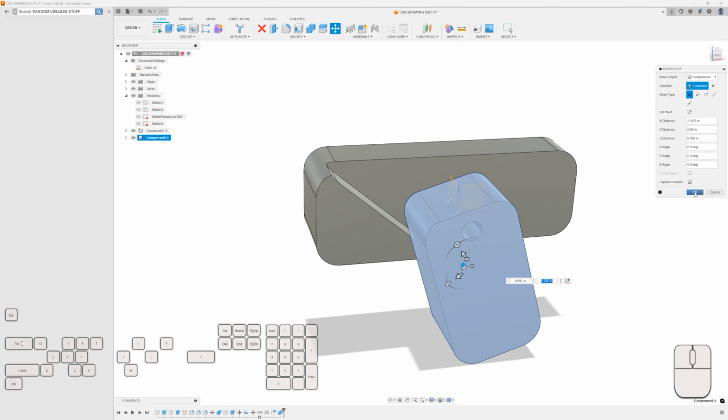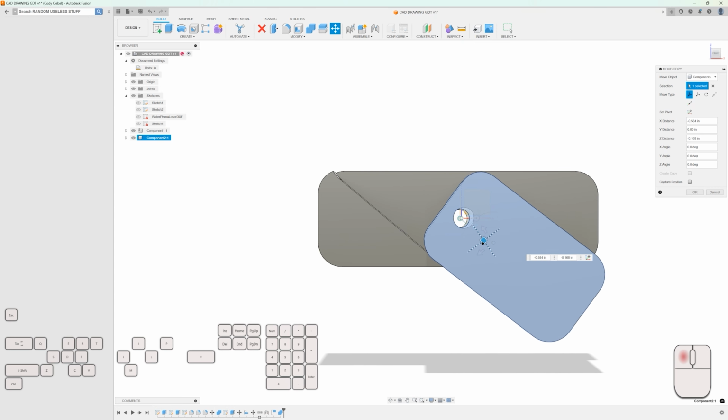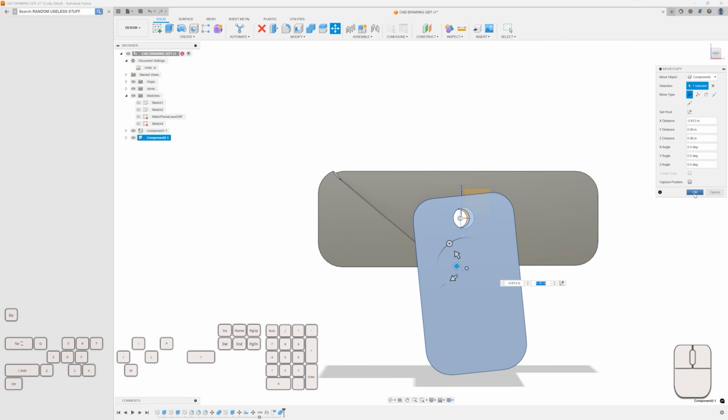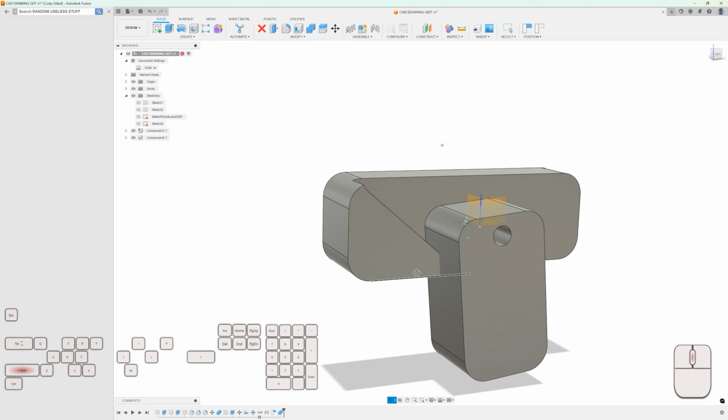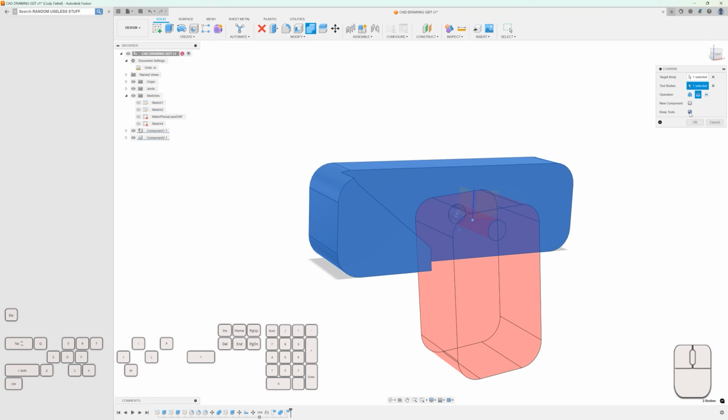And we can kind of give our rotational limits by doing the same process. So maybe I want the maximum rotation from this end here to stop right here before it hits this metal and gets stopped. Or maybe right here we're putting a switch for a machine we're designing that's computer controlled, and we're looking for a limit switch to get hit right here. So we'd have a little switch we design. So we're going to click combine, capture position. We're going to click that.